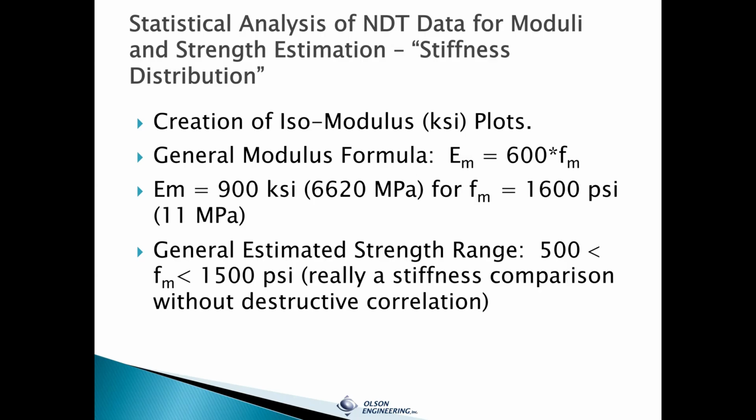We did measure the in-place modulus, but he was going to approximate it, and he knew the strengths were going to be higher than predicted, but he was getting the stiffness of it. And that was important in his analysis from an earthquake response to get this relative stiffness. And I'm sure ultimately he applied some other factors to that to reduce the strength to something more reasonable, because nobody really thought that the old brick masonry was 1600 psi. That was about the maximum.